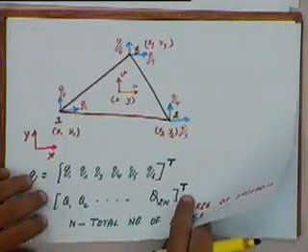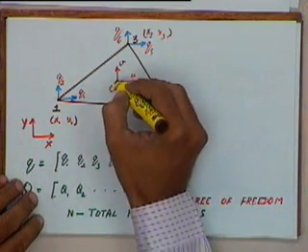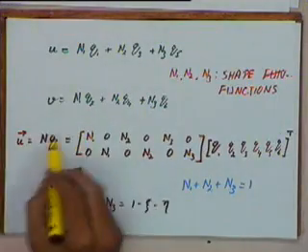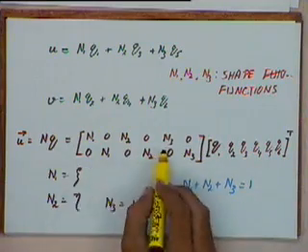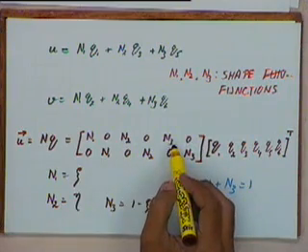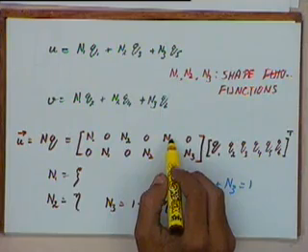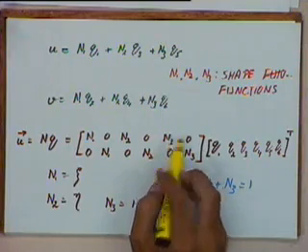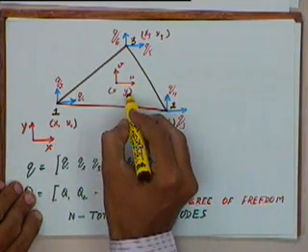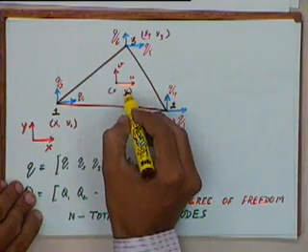If I am taking any particular point over here, I am trying to find the deformation at this point. This relationship gives me the relation between u and q as a function of n1, n2 and n3, but I am yet to relate n1, n2 and n3 with the xy values, the location of this point x and y. I have to specify n1, n2 and n3 as a function of x and y.